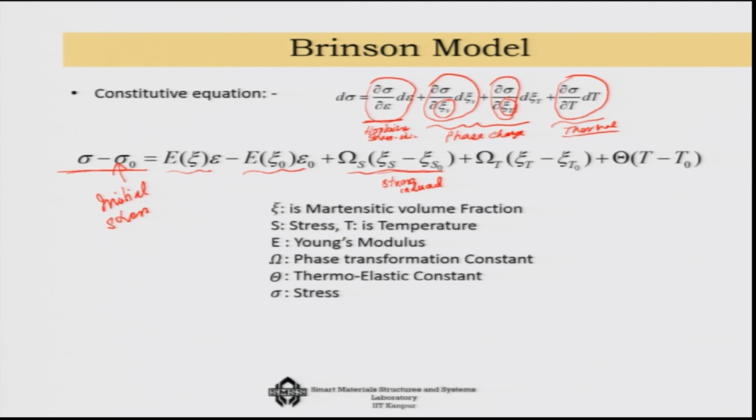Earlier it was simply Ω times ξ itself, the total phase transformation factor, ξ at any stress and temperature minus ξ at 0 stress condition, but it is Brinson who divided this into two parts: one is the stress induced and another is the temperature induced. And finally, just like that last expression, you have this thermal part. So, that is the constitutive relationship that we will be using for modeling of the system.